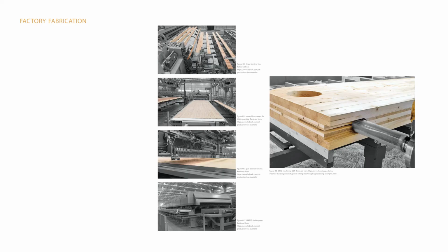Prototyping. The design of a connection system such as this means very little if it can't be applied to industry. Though there are differences in every factory, the base procedure of creating a CLT panel is the same. Timber lamellas are sawn down and finger jointed before being sorted into long and cross laminations. They are then stacked at 90 degrees to each other before being bonded and glued.